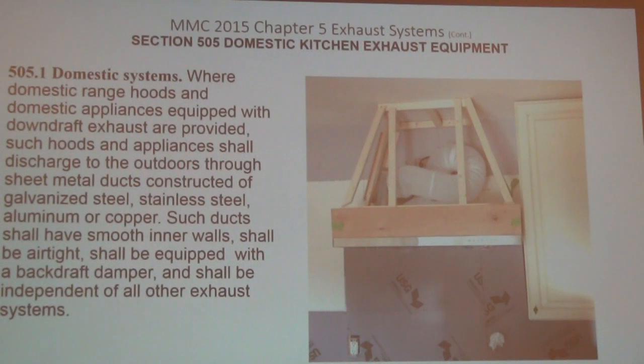And I'm not trying to step on anybody's foot here, but I noticed in some municipalities, they will not allow you to use sheet metal screws in the joints. And that is a misinterpretation of the code, because in the Michigan Residential Code, it will reference you that the ductwork has to be done according to the duct chapters, 15, 16, something like that in the residential code.